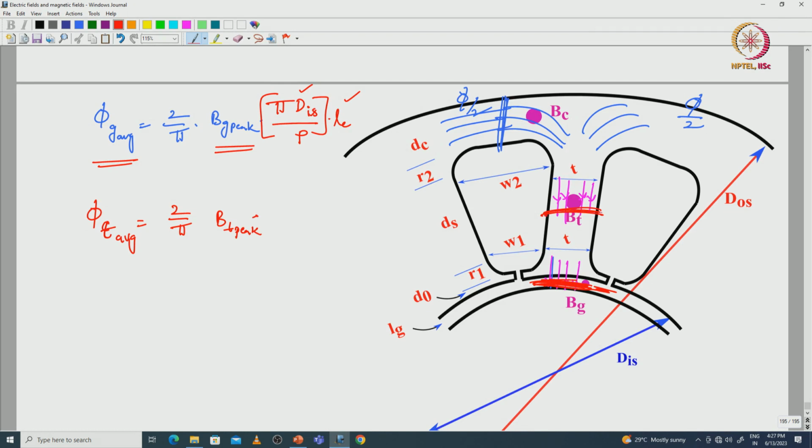into what is the area with respect to this cross section. The x axis length will be T into Qs, and the y axis length will be Le into Ks. Here Ks is the steel stacking factor or stamping factor, we can select it. Okay. Steel stamping or steel stacking factor is nothing but this one. So, from this equation by P should come with respect to per pole, T into Qs by P is the x axis length and Le into Ks is the y axis length.